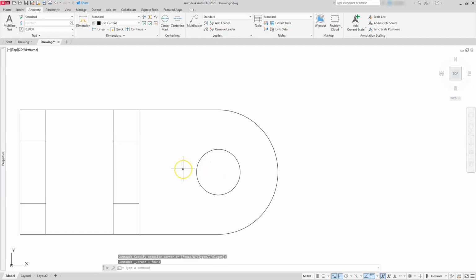And what I like to do is if I'm creating a metric drawing, I'll set my center mark extension line set to somewhere like 3 or 5. Either one of those should be acceptable. But the command to use that one is going to be called CENTEREXE. Enter. Now, with this number, I'm going to set it to, let's set it to 5 for this example.